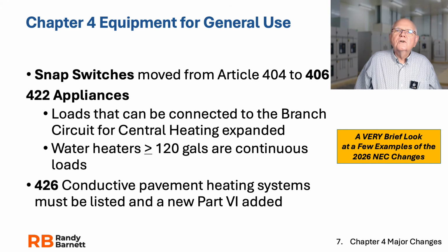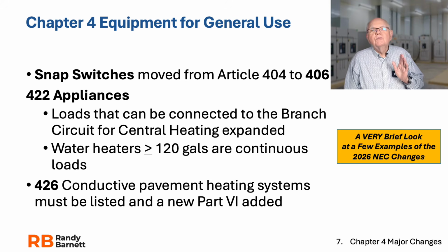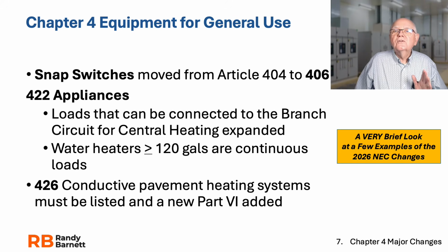Anyway, 422 on appliances applies to all types of occupancies, not just dwelling units. At 422, it now lists loads that can be connected to the branch circuit for central heating. That has been expanded. Okay? So if you're involved in any of that. Water heaters made it clear that water heaters greater than or equal to 120 gallons are continuous loads.